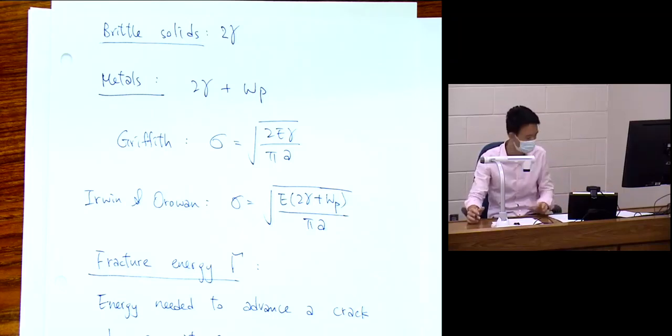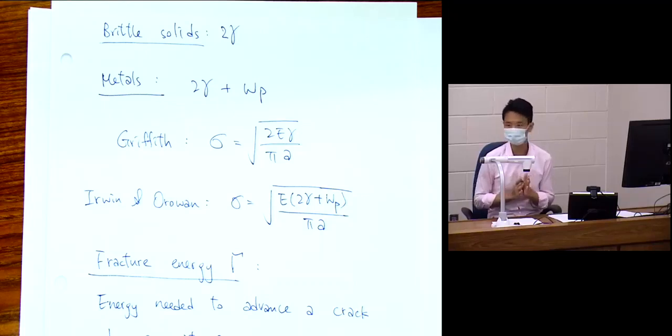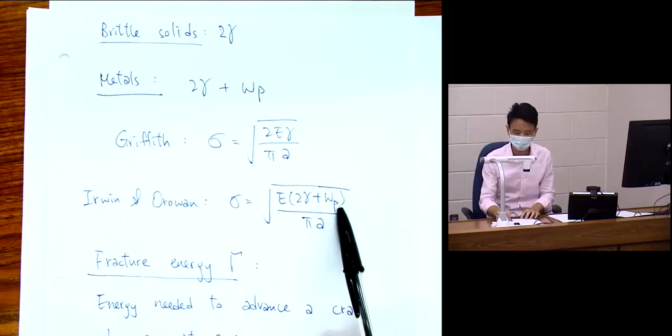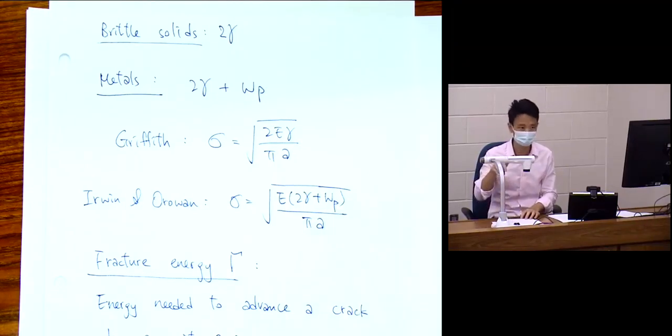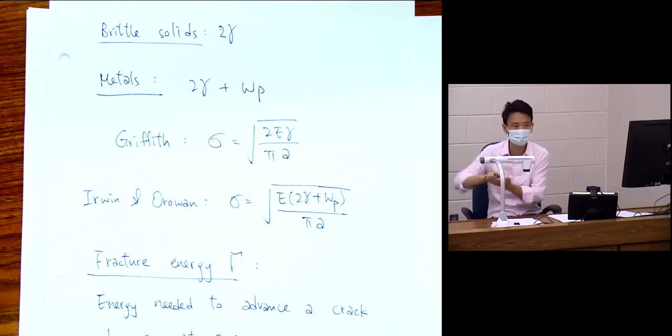So if you know a little bit about plasticity, when steel yields and deforms plastically, you have dislocations of the crystal planes. That is a microstructural process that happens when you have permanent deformation, right? There's dislocation, slip planes, that sort of thing. Now, all that deformation, that change in the microstructure, requires energy input. So that is what this WP is physically, right? The energy goes into dislocating the planes, slipping the planes along each other before you can break them.